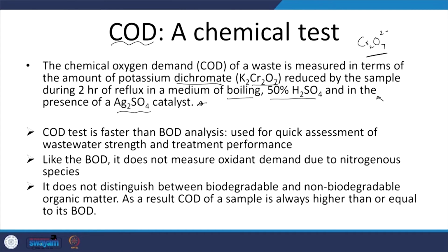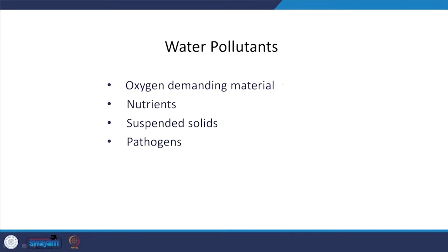And again, both biodegradable and non-biodegradable, but one aspect is similar to the CBOD test. Even the COD test will not oxidize or lead to oxidation of your ammonia. So, that is something to keep in mind though, right. We have spent considerable time on oxygen demanding material, but that is worthwhile because during water and wastewater treatment we are always concerned with oxygen demanding material.